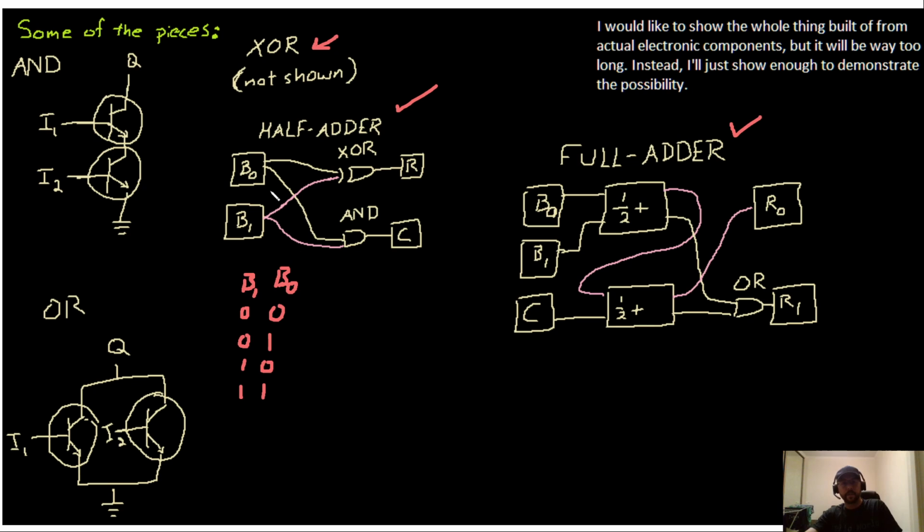And so what this is telling us, the half adder, is that this is exclusive OR. So this means if either of these is a 1, but the other one is a 0, then our result becomes a 1. And that's represented here and here. So that means if you're adding together two bits, 0 plus 1, or 1 plus 0, then you want this, which you imagine this turned on its side.